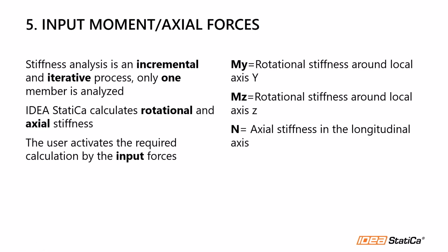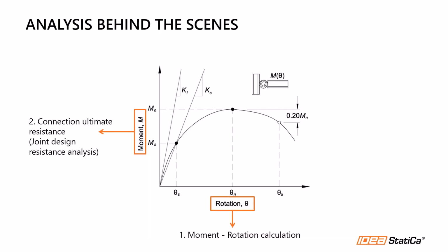All right. Now let's continue to the next slide. So once you set up the forces and then you hit calculate, let me explain what happens behind the scenes. To get the moment rotation curve of a connection, IDEA does two types of analysis internally.